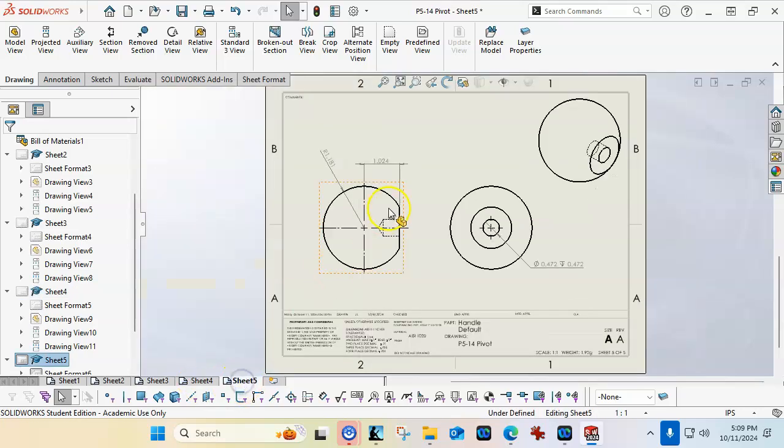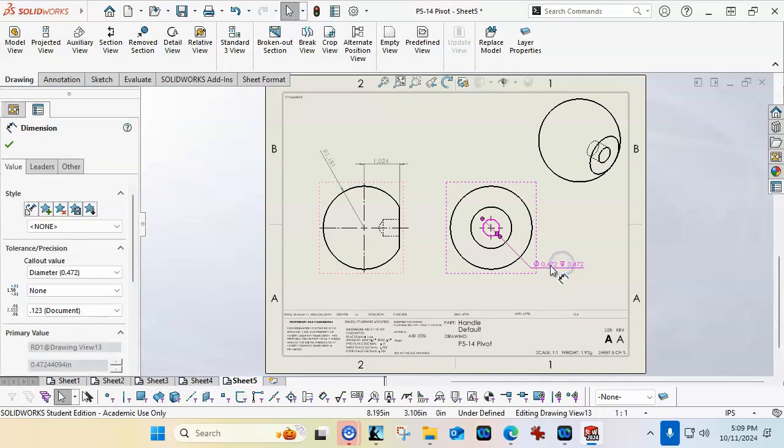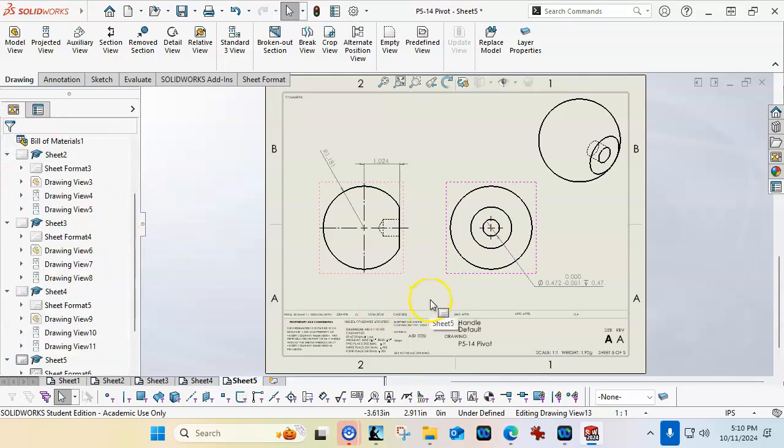And when we come over to the handle on this side, we can pick the diameter and the depth. The depth is not real critical. We might move it to 2 decimal places to be generous. But on the diameter, I would also want to do a bilateral, and it would be a minus 0.001 for the fit. So 2,000ths.